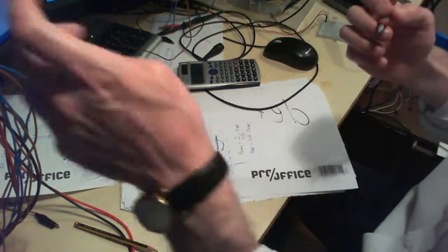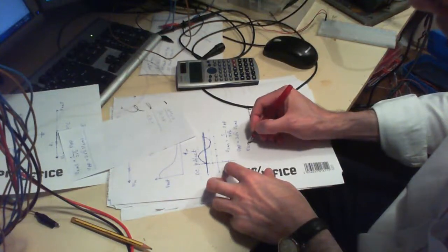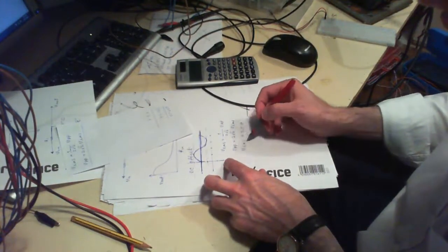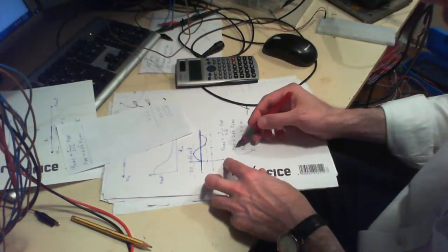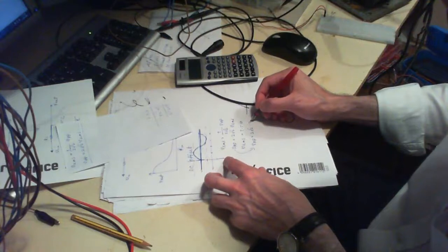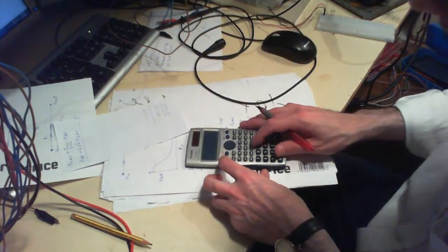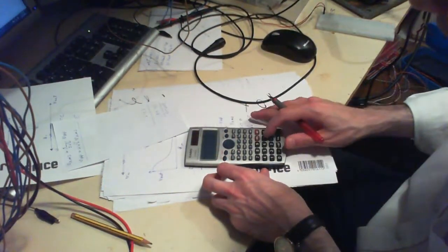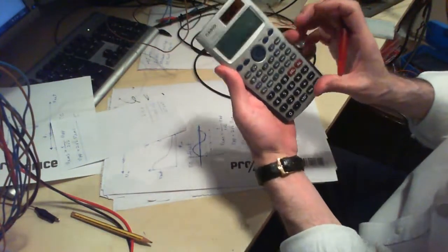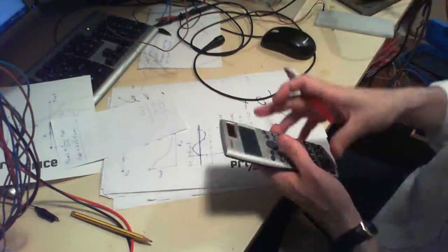Now, the RMS voltage that I read over here was 3.5 volts. So V of RMS was equal to 3.5 volts. If I put this in this relationship, V of peak-to-peak would be equal to 2 square root of 2 times 3.5, which is equal to 7 square root of 2, which is equal to 9.9 volts, meaning 9.9 volts peak to peak.